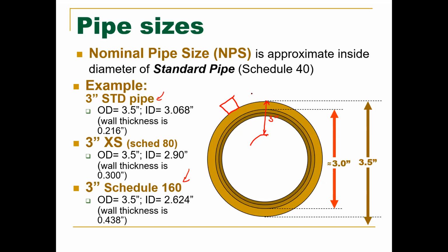Within 6 months of putting in that 3-inch walled piping, we had to start doing what were called UT scans. Basically, they sent a wave in and it would tell you the actual wall thickness. That 3-inch armor plated steel was down to a quarter of an inch in some places after 6 months of use.